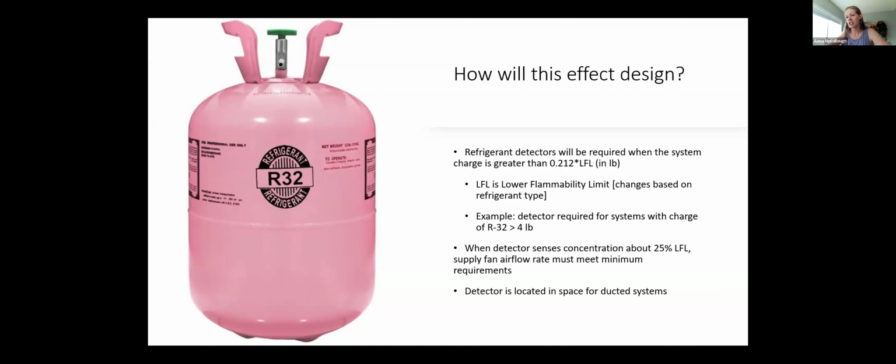And we also recently, shockingly, had an architect suggest putting the refrigerant lines on the outside of the building and protecting them in a shaft that is located outside of the building. So rather than taking the shaft within the thermal envelope of the building, we're including it on the outside of the building with a protective metal encasing around it. It's like a little block coming up the outside of the building. And that is what we've come up with so far. I wish I had more solutions.